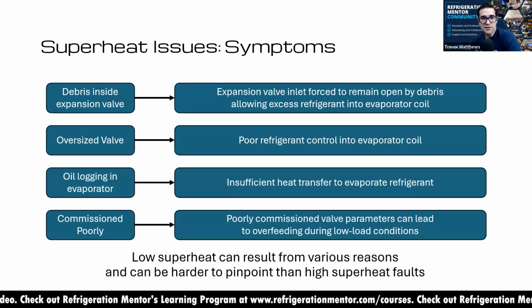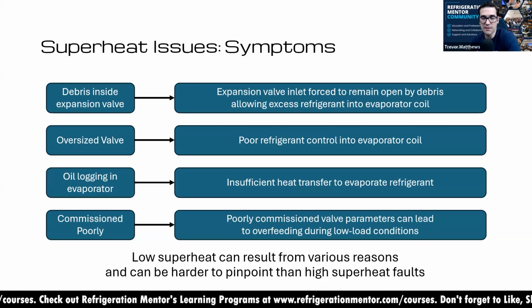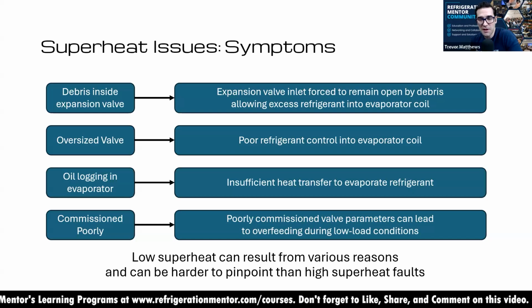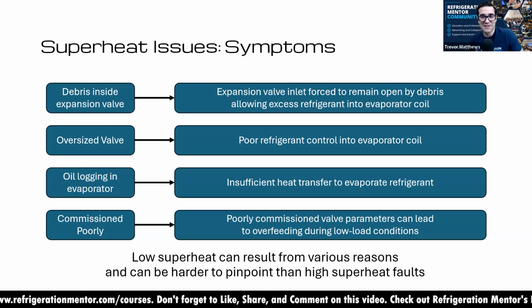And the very first point there, Chris, debris inside the expansion valve, I think that is one of the biggest ones. When I used to work for the manufacturer doing a lot of electronic valve training, I would go to events and talk to all the competitors, and we had the same thing as a manufacturer. Most of the issues were debris inside the valves. This is something you really want to take a look at, because all the big valve manufacturers are doing a good job. They've got quality control, they're spending millions of dollars to make sure a good product comes out. Do issues happen along the way? Totally do. But there should be absolutely zero dirt or debris inside a refrigeration system.